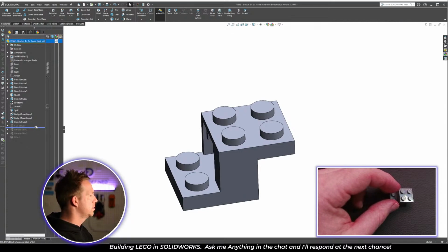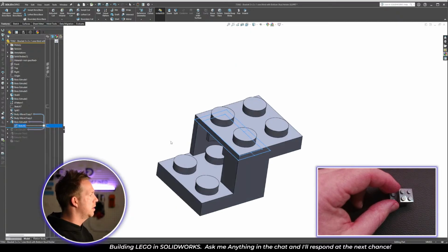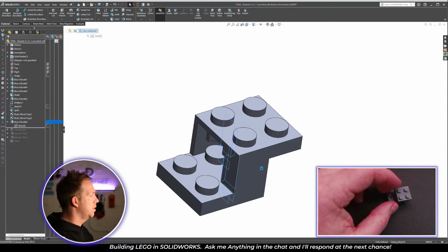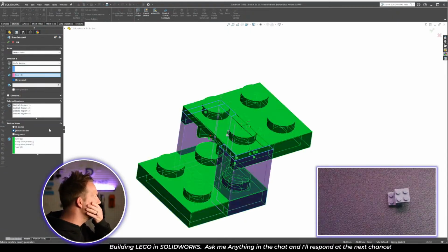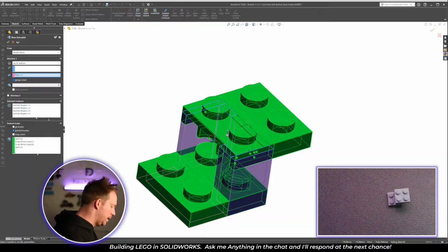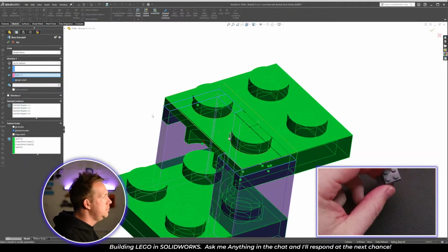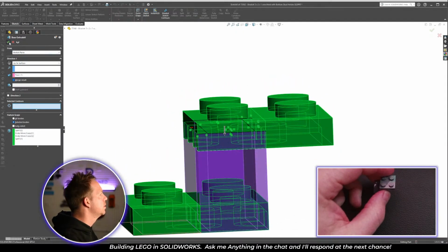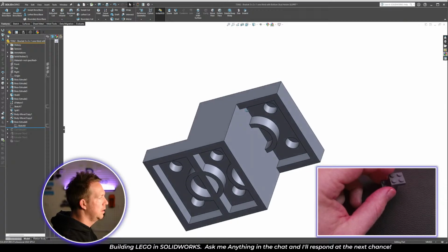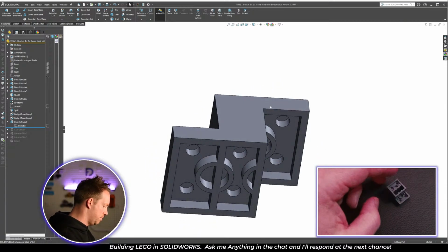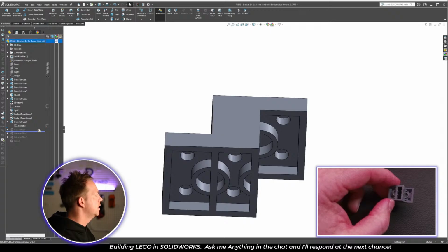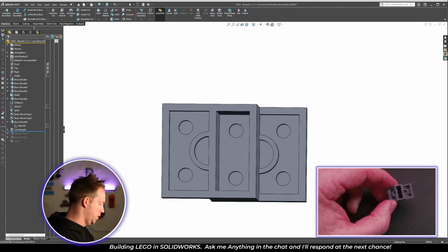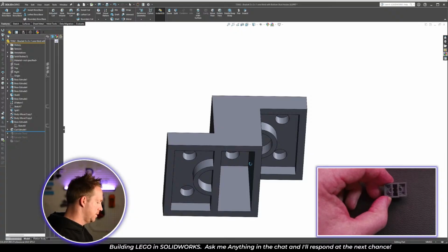The extrude works. But it appears I might have to select some different contours. So I'll just go into the feature itself, and I'm changing the regions. And I'm going to delete all the regions because I want to use that whole sketch. Kind of seals it up. All right, that's looking much more like what I can see here. And then the cut, good. That cuts exactly as I expect.